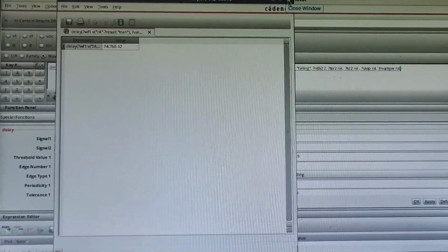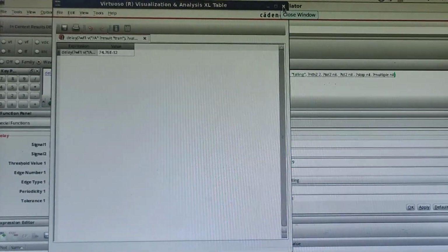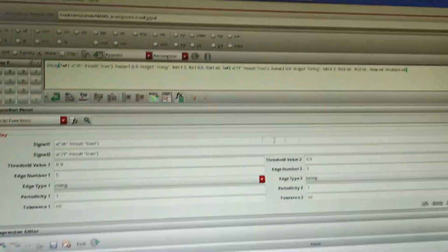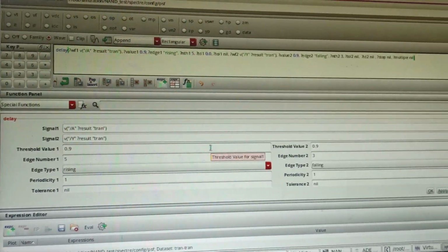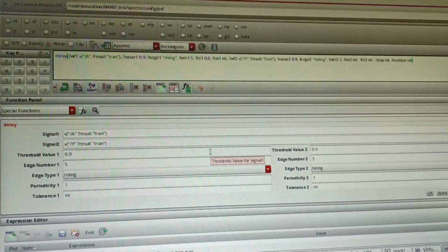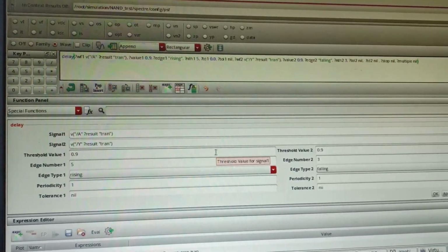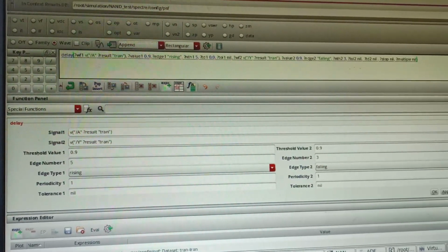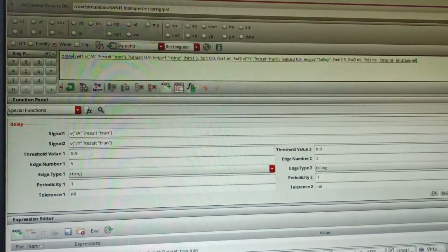This completes the delay computation after doing the layout, that is post layout values. Obviously, the results obtained for post layout simulation will be more than the pre layout simulation values. That's because we are including the R and C values for the simulation. This completes the back annotation process.